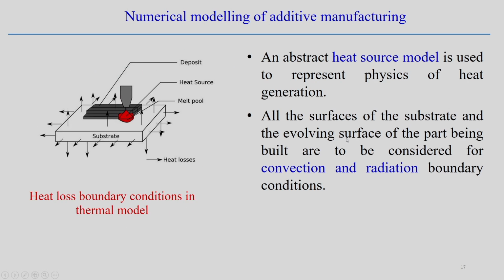Now, not only the governing equation, we have to look into the boundary interaction, or boundary condition, in this case. If you consider the substrate material with the deposition as a whole solution domain, what are the activities on the boundary? Over the boundary there will be heat loss to the surrounding by convection and radiation. That is one thing.